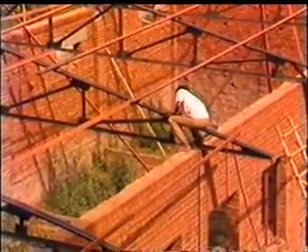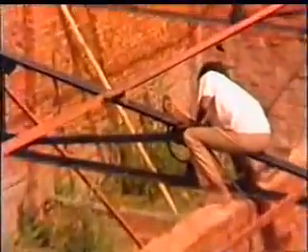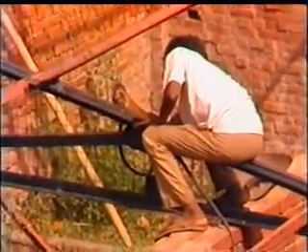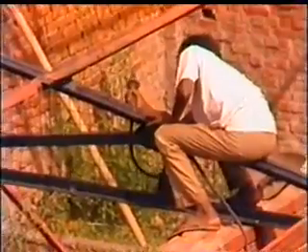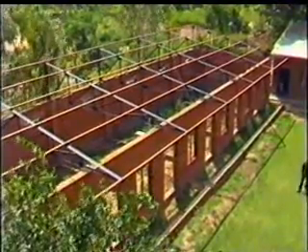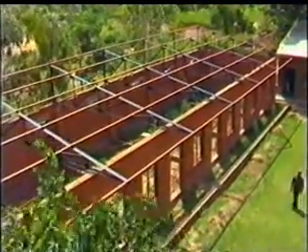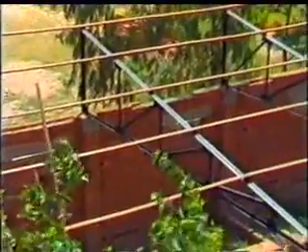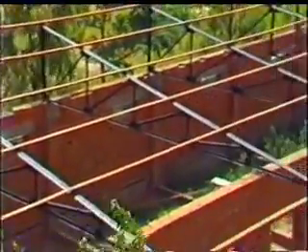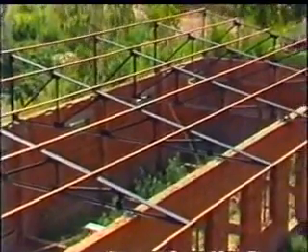The purlins support AC sheets and transfer loads to the truss joints. Spacing of purlins is so adjusted that the cutting of sheets is avoided, and normally it rests over or very near to the joint.